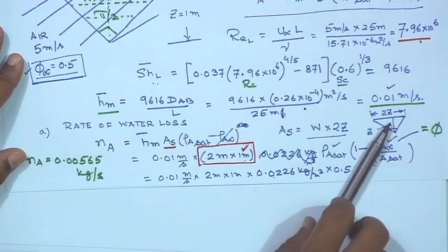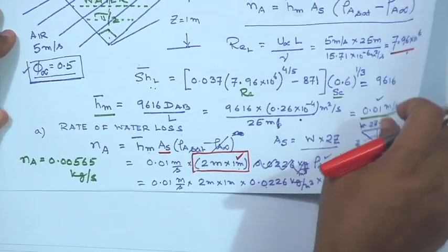What it tells you is that the evaporative water flux is a constant, but since the surface area is changing with evaporation, the total rate of water which is going from the liquid to the vapor phase will vary. So, the rate in kg per second will change, but the flux in kg per meter square second will not change. So, that is something which we can clearly see from this expression, and now we are in a position to do the second part of it.